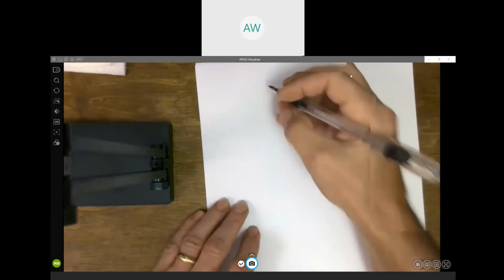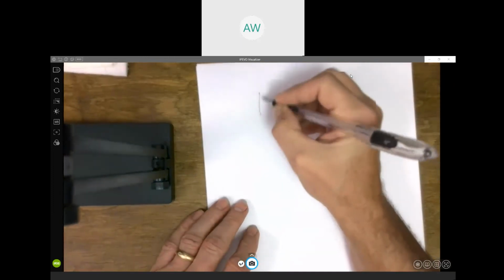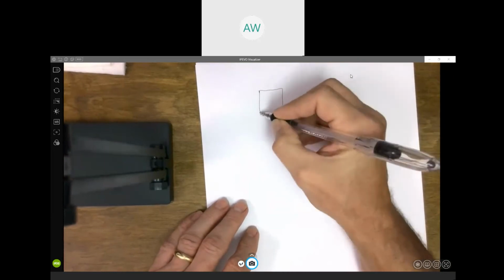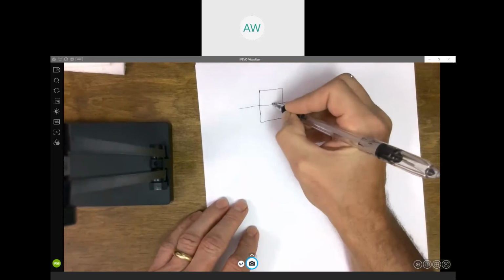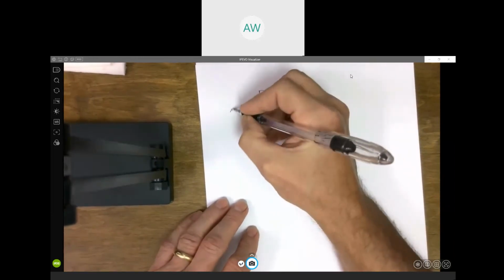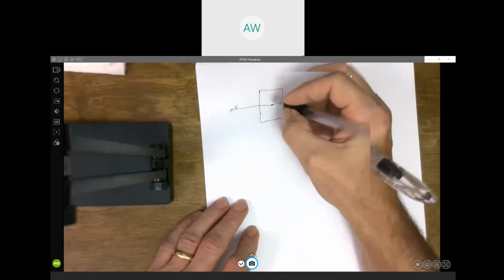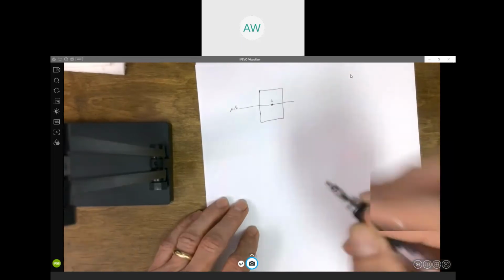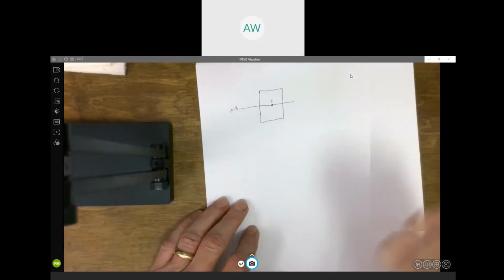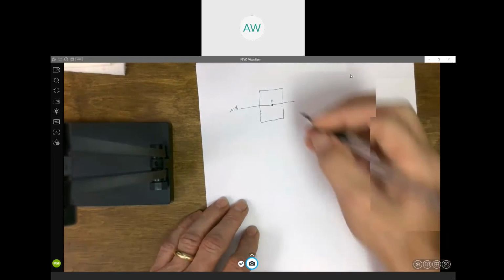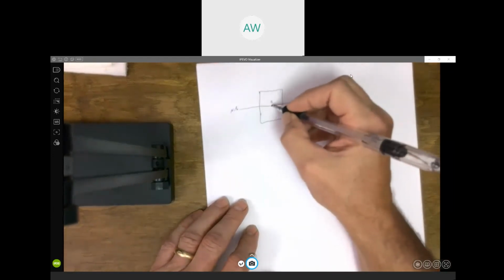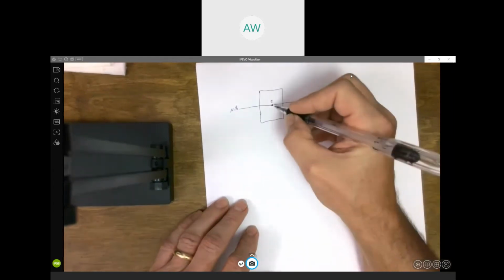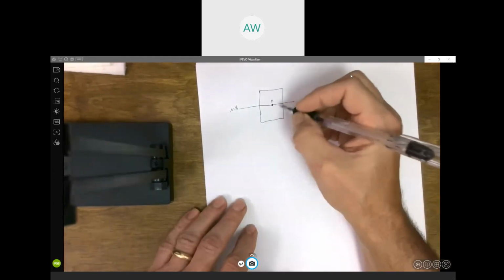Say, for example, we just have a rectangular cross section like we did in that first example. So we know the neutral axis goes through the centroid of the whole thing. Now, in this case, the centroid of the whole thing corresponds to the centroid of this piece.